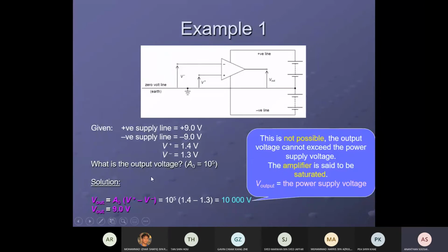No questions. So understand, the operational amplifier can give any output, but who is going to give the output is the supply. If the output instructed by the op-amp exceeds the power supply, the output will be saturated to the maximum value of the power supply.